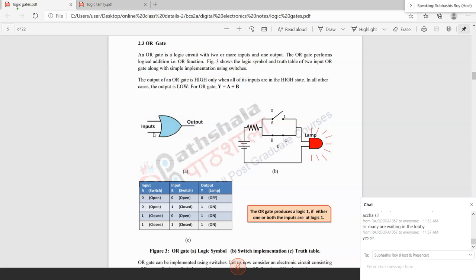Okay. So if I draw this circuit, how can I draw it? So this is the drawing of the circuit. We see one input is connected to 1, so B is fixed to 1, and one input is varying so that I can get different states of the circuit. If switch A is connected to 0, you are still getting output. And suppose A switch is connected to 1 and B switch is connected to 0, then also you are getting output. When there are two parallel paths, current can pass through either path, depending upon the switch position.